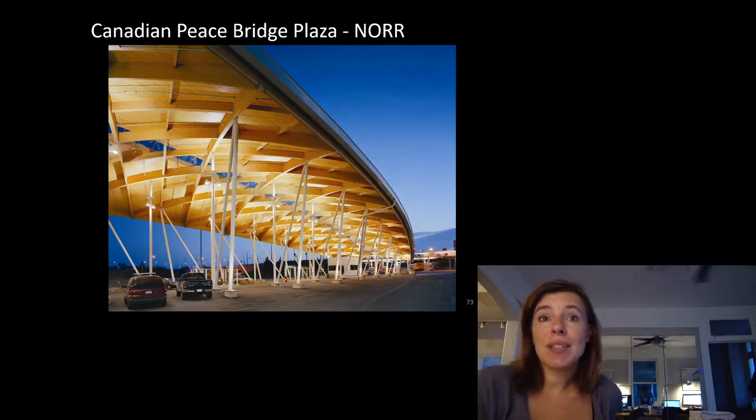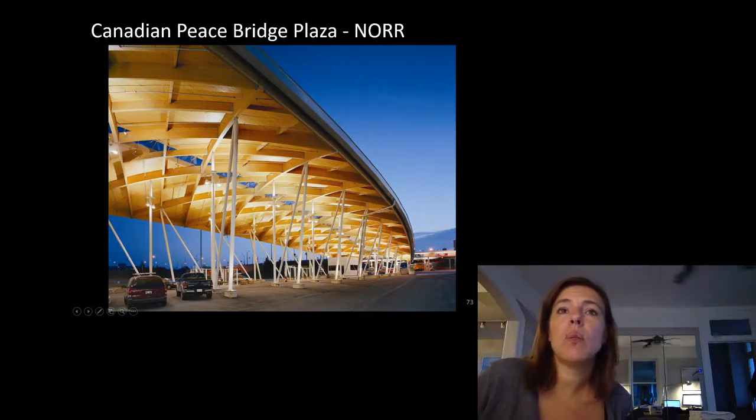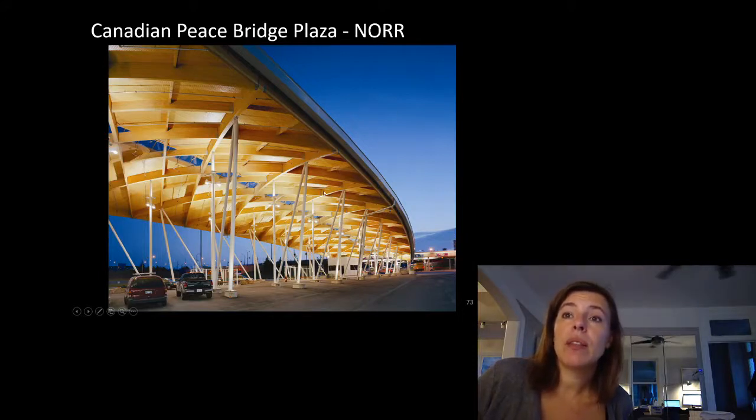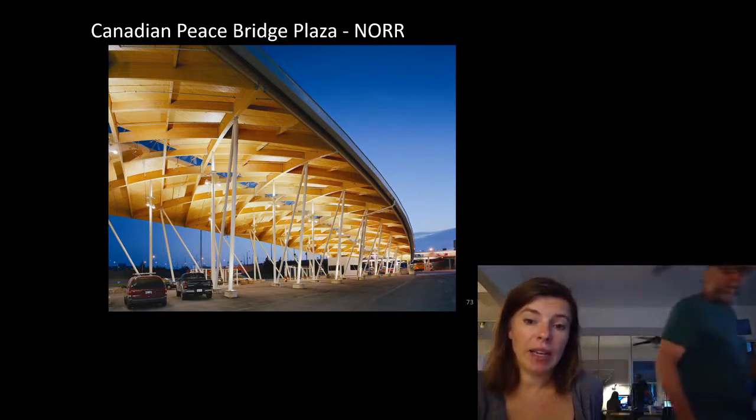This, as much as it is a building, is a canopy. So there was a building down here and a building down here at this end as well, but you can probably consider this a canopy because it had wind coming underneath and wind at the top. When working on this, I certainly didn't think of it as a canopy. I mean, I did for calculating the wind loads.